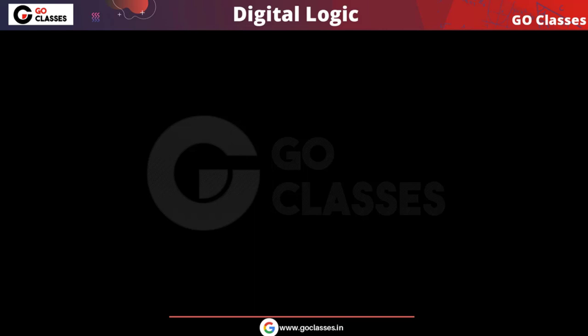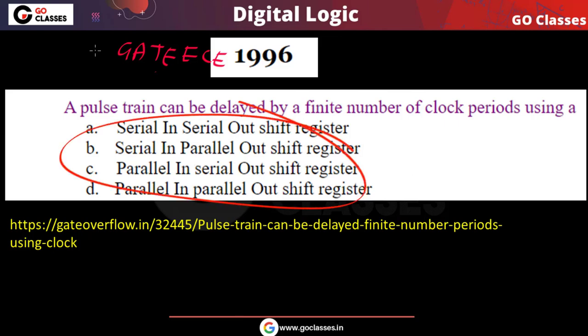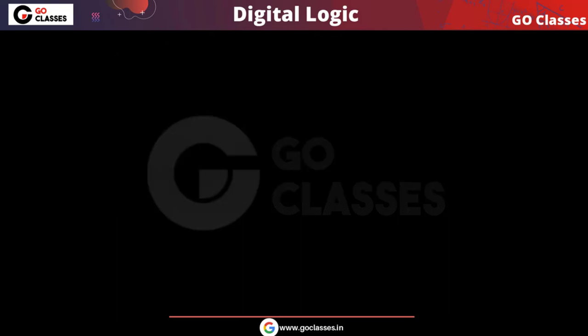Now you can solve this question. This is a 1996 GATE question in the electronics branch, and you can solve it very easily. It says that a pulse train, basically a data stream, can be delayed by a few clock periods using which register? We have already seen this: if you want to delay a pulse, that is an application of the serial input serial output shift register.